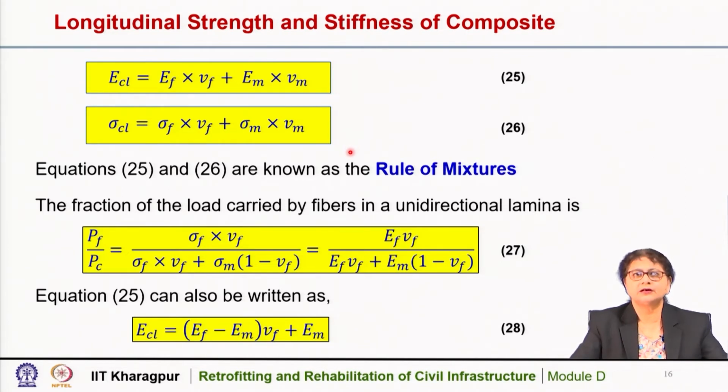So, to determine the elastic modulus of composite, the rule of mixture can be applied, and by knowing the volume fraction of the fiber and the volume fraction of the matrix and their elastic modulus, we can find out the elastic modulus of the composite in the direction of the fiber. Similarly, the stress in the composite can also be obtained from the rule of mixture.